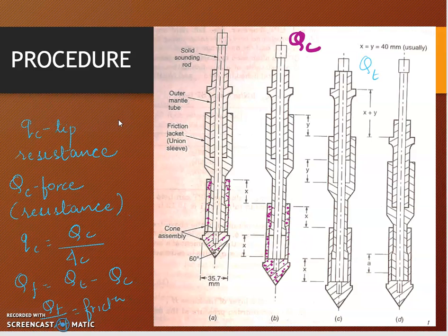Okay. Now, let's go to DCPT. DCPT is the dynamic cone penetration test. In the dynamic cone penetration test, this also has IS guidelines. DCPT is either performed by using a 50 mm dia cone with or without bentonite slurry, or by using a 65 mm dia cone with bentonite slurry. So if you are going to increase the diameter of the borehole, bentonite slurry is mandatory.